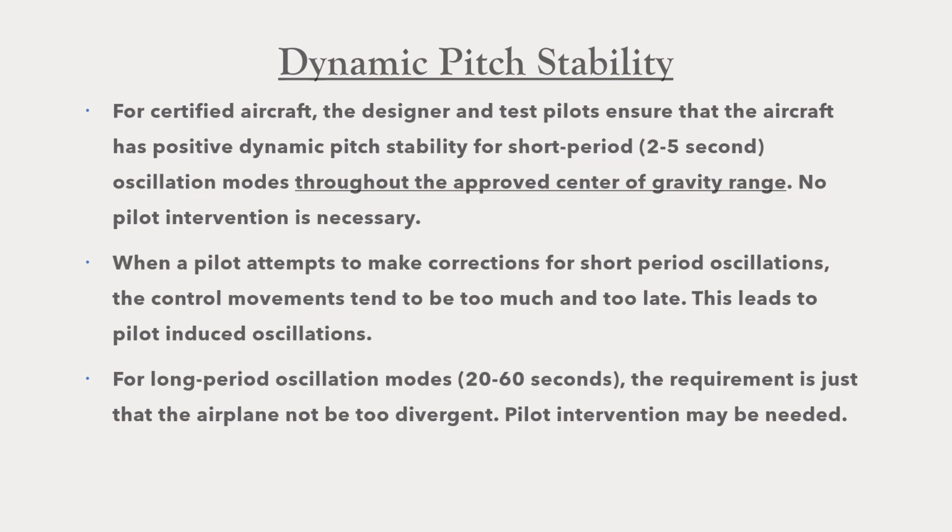There's also a long period oscillation. This is related to the tendency of the aircraft to start climbing and slowing down while it recovers to its pitch attitude. This oscillation mode is much longer. The certification criteria is simply that the airplane not be too divergent, to make it too difficult for the pilot to control it. So some pilot intervention may be needed to deal with that, but it is not difficult to do.